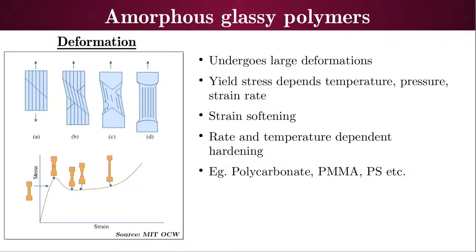First of all, regarding amorphous polymers, I will be mostly talking in a continuum manner, no molecular level things. If you look at the deformation behavior of an amorphous polymer, when a strip of it is loaded, initially it shows an elastic or more or less viscoelastic response. At some point shear bands appear, and they go to an instability region, which shows a yield like behavior the way we generally see in metals.